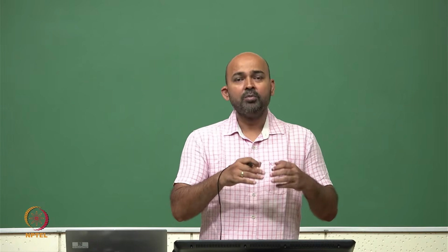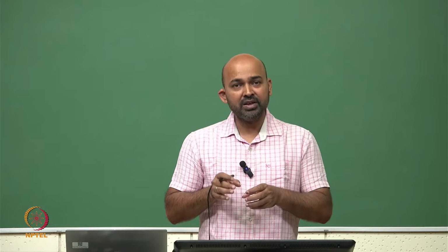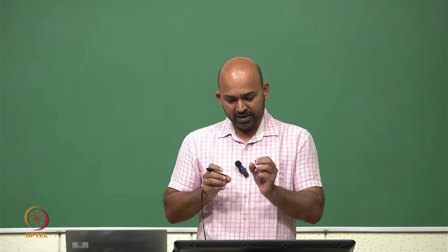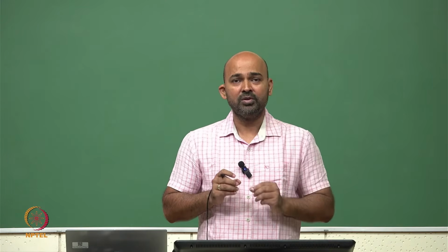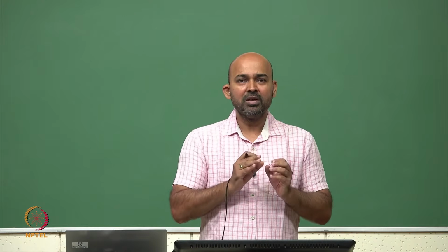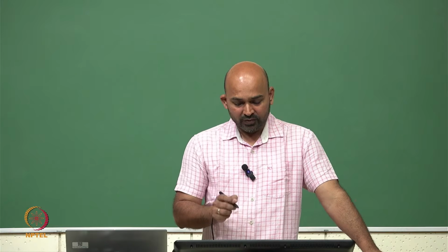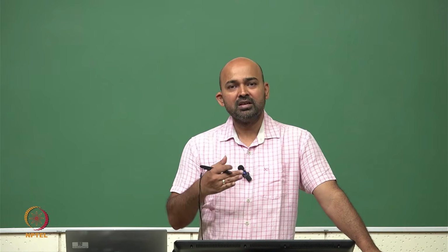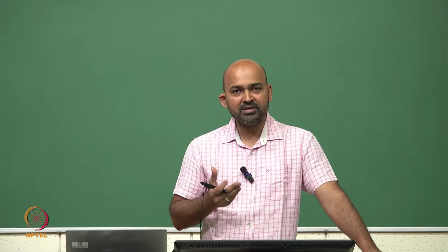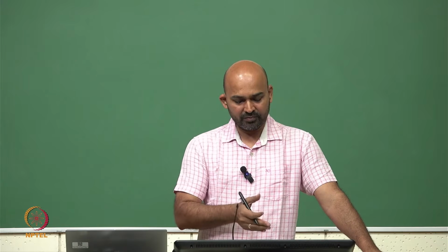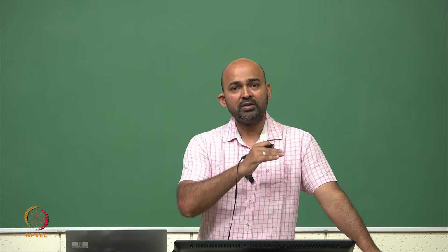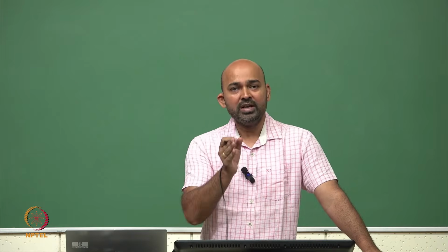So, our computational time increases if we make V increment a very small value. So, we put it reasonable so that the computation time is within limits and we analyze the circuit accordingly. So, V increment is generally a parameter which we choose very wisely in going from V start to V stop, so that we do not miss out on any particular value.